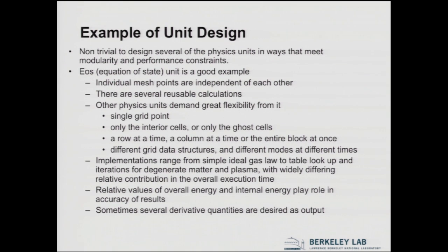Then again, when you're dealing with anything more complex than an ideal gas equation of state, there are a lot of computations that are reusable from point to point. And if you really do it in a form where you're going from one point to another, you're not making much use of your spatial proximity and reuse of cache. So you want to be able to vectorize them also. So you have all of this in front of you, for which you have to devise an interface that doesn't intimidate a person just as soon as they look at it.